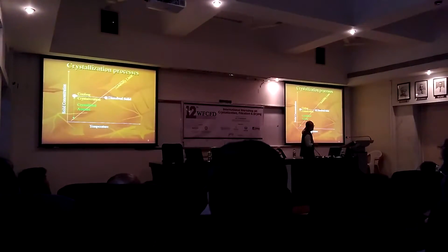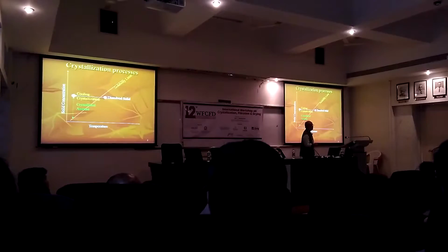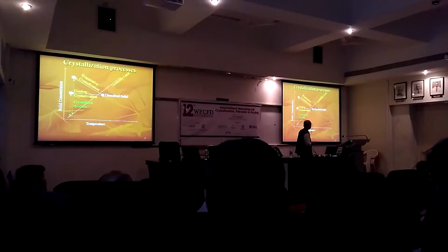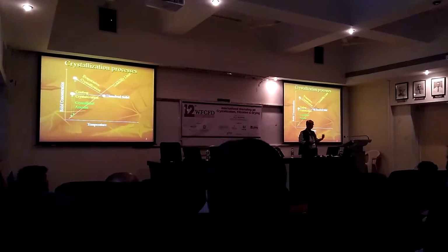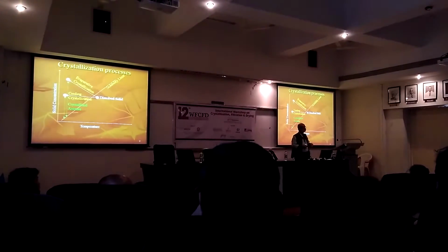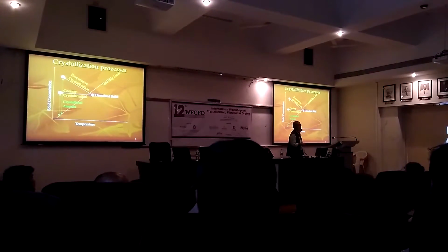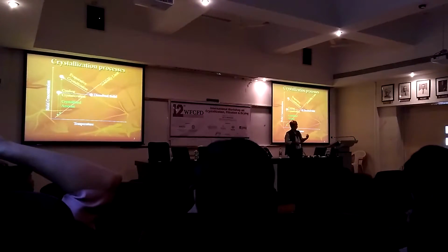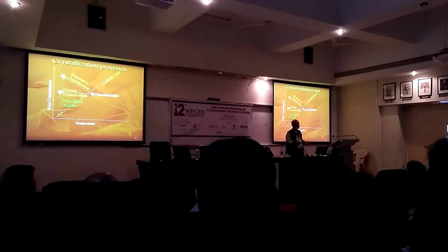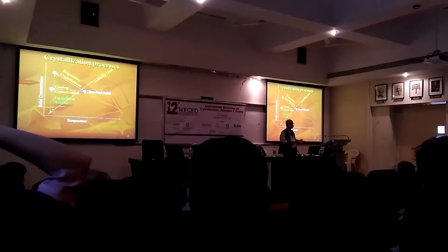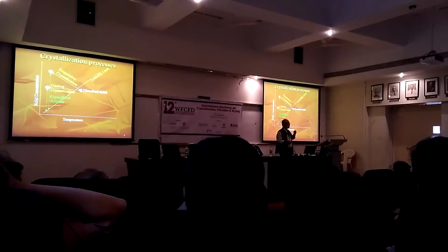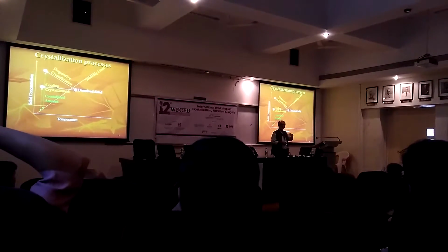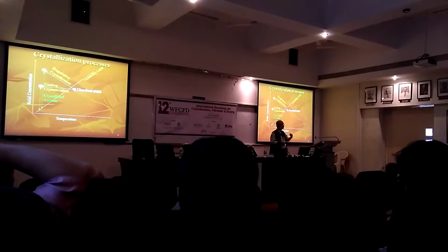But the difference between the saturation solubility point and the actual conditions is the quantum of solute which is going to precipitate out. Alternatively, you can evaporate part of the solvent so that the system becomes again supersaturated, and as you can find from here, the quantum of crystals which are going to crystallize out, or the solute which is going to crystallize out, is likely to be significantly higher. However, evaporative crystallization needs to be accompanied by cooling, followed by cooling, for you to get higher recoveries.